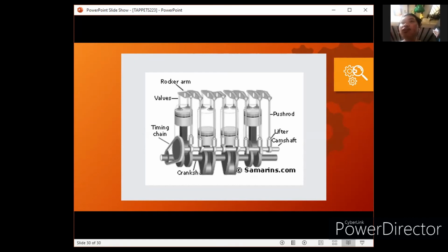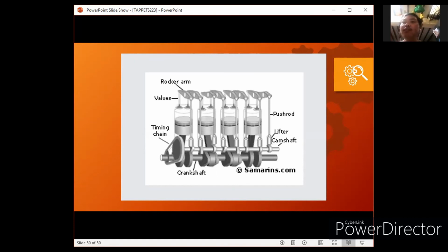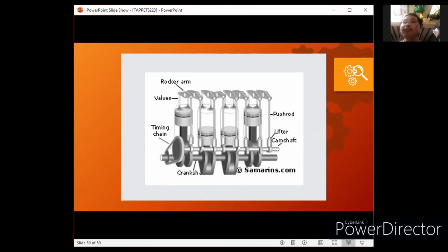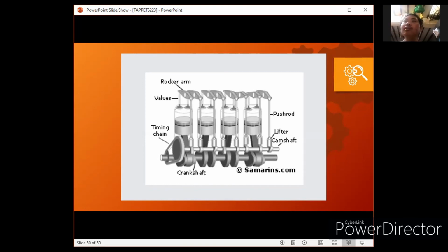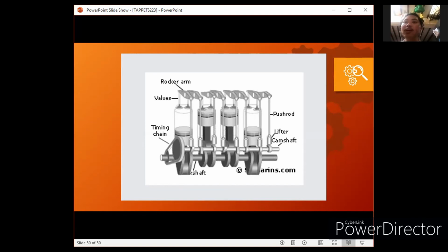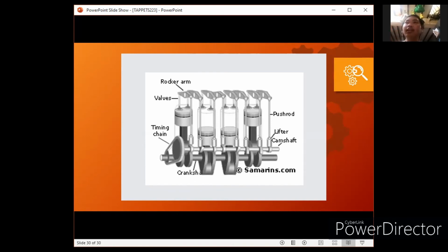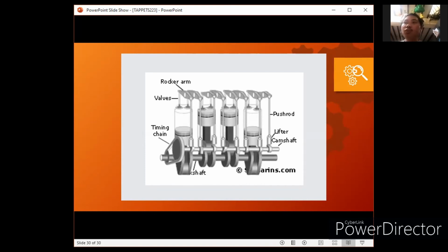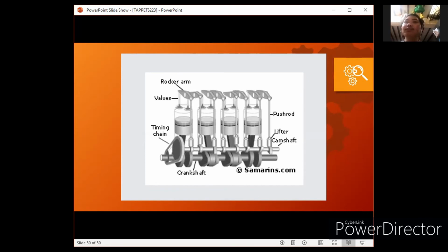So, to prevent that, a constant flow of oil from the reservoir towards the push rods and to the rocker arms must be ensured, and this system must continue to operate on a regular and consistent basis, since this is basically what makes the cylinders operate. Without these systems operating at normal functions, the engine itself would basically not work. So always maintain the parts of the system in peak condition.